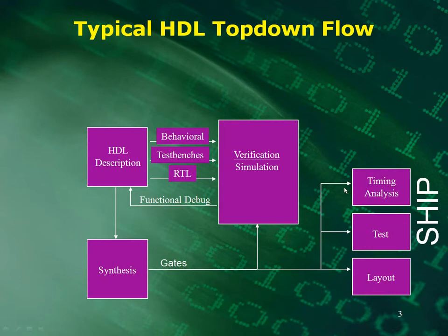Once you finish that, you're probably going to want to do some timing analysis. The tools such as Xilinx's ISE tools and Altera's Quartus tools have built-in timing analysis tools, and you're going to want to use those to see that your design meets timing.